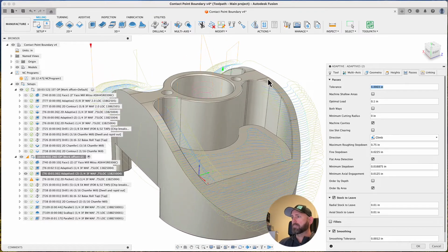But what's happening in the background is, and this will make sense as we're looking at other toolpaths later, every CAM system I've ever used, and it's probably 7 of them, a tessellated model in the background gets created, and it actually gets created based on this tolerance. There's probably some other geeky stuff that I'm unaware of, and those tessellated, kind of triangulated surfaces are what is showing up in these corners.